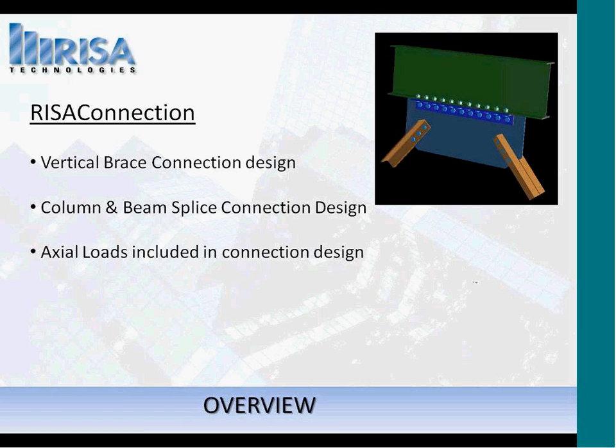We have also added axial loads into connection design. So you've had moment and shear, and now you're going to see axial loads coming through. This is in particular the most important piece when it comes from RISA 3D or RISAFloor. If there are any axial loads, those will automatically be brought into RISAConnection for you. We also added DXF export of the connection details. When you're looking at the two-dimensional pictures in RISAConnection, all of those can be exported directly into your DXF format, so you can prepare your construction drawings directly from that. We'll see an example of that too.